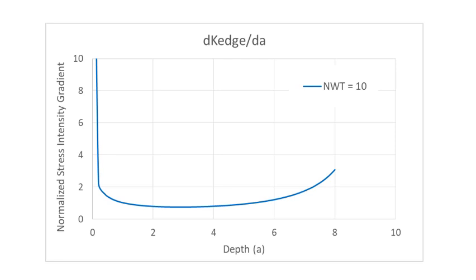So it's fairly interesting to me to see that our crack grows from a very unstable form to a more stable form to a less stable form during its propagation. And I'm not sure if any of you have seen a plot like this before, but it really reminds me of something that I've seen in the stress corrosion cracking literature.